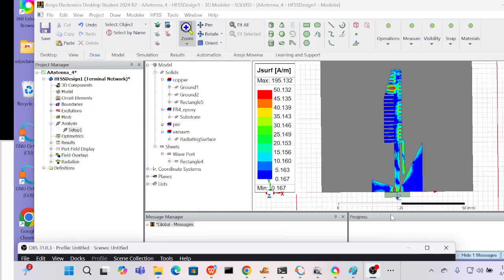In this video, I'm going to show you how to display the view, the surface color in this manner. In your HFSS design, you might be interested in the color distribution, the field distribution, and this video is for you. So the first thing that I need before doing anything,